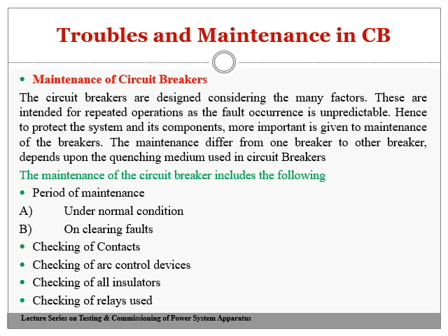The maintenance differs from one breaker to the other. There are different varieties of breakers available, and the maintenance aspects or criteria differ from one breaker to the other, depending upon the quenching medium used in the circuit breaker. We've already seen that circuit breakers are classified depending upon the quenching medium. That's why, as the quenching medium differs, different maintenance methods are available for the particular circuit breaker.